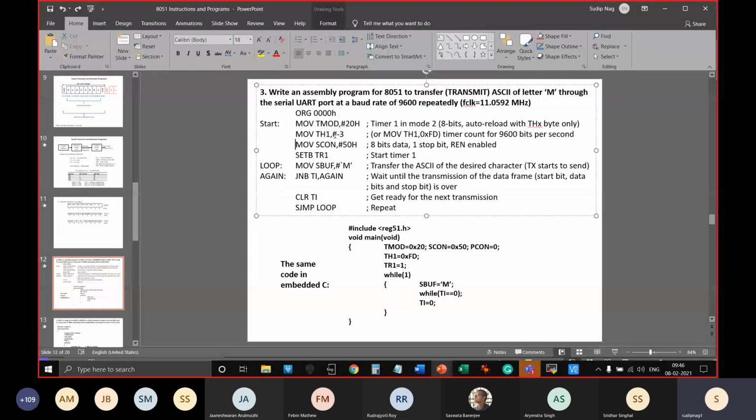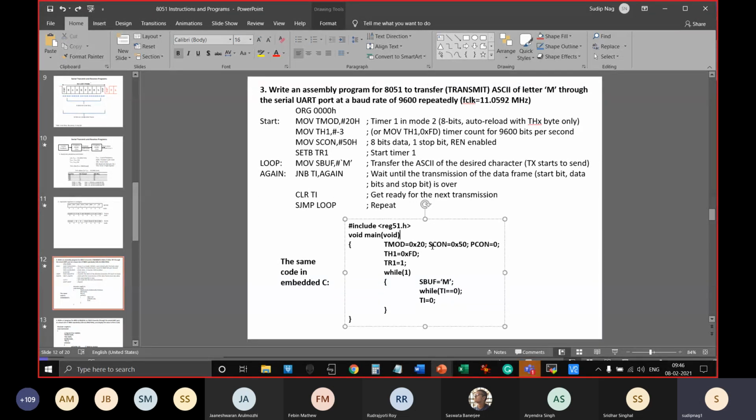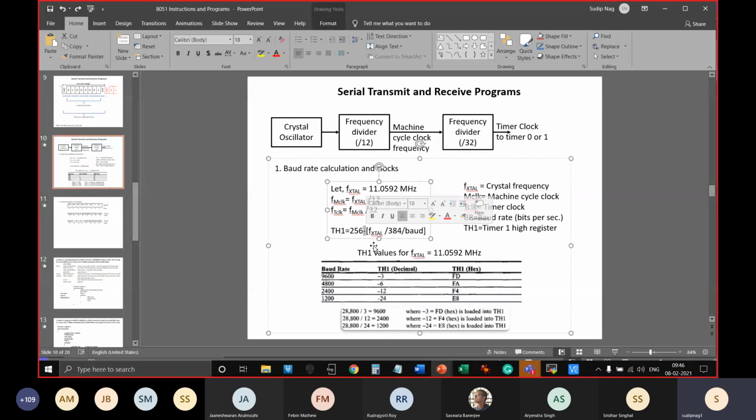Okay, so while down counting, you have to subtract it from the maximum value, that is 256, because the maximum value is 256. That means you will get only the remaining number of counts that you can have within the 8-bit width. So that is why it is a minus in the equation. It is different from this minus, obviously. This 256 minus comes because it is down counting, it is not up counting. Overflow happens after it comes to 0 from a given initialized value. So that is why it is so.